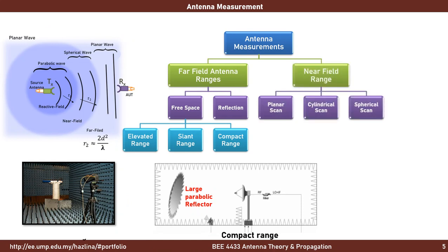The dimension of a conventional test range can be reduced by making the measurement in the near field of the antenna under test, and then using an analytical method to transform the measured near field data to compute the far field radiation characteristics. Such techniques are usually used to measure patterns and gain. The near field measured data, amplitude and phase distribution, is acquired by using a probe to scan the field over a pre-selected geometrical surface, which may be a plane, a cylinder, or a sphere. The measured data is then transformed to the far field using an analytical method.